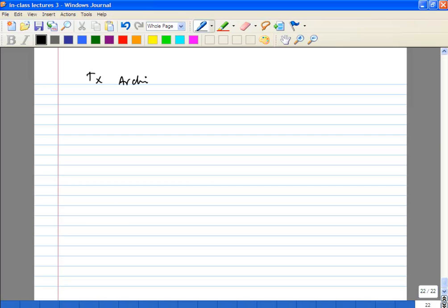Yes. So why is there such a large difference in the IIP3? Because in one case you're specific. In one case you just want to make the switches extremely low resistance. You want to make it zero. You don't expect the resistance to vary based on the RF voltage.